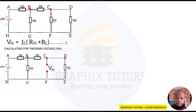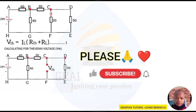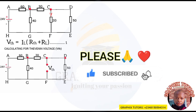So now, how can I make the current through this 5 ohm resistor become a voltage? When current flows through a resistor, there will be a voltage drop. That voltage drop, because parts DE and CF are in parallel, we say they are the same. So my VTH will be whatever my voltage drop will be.